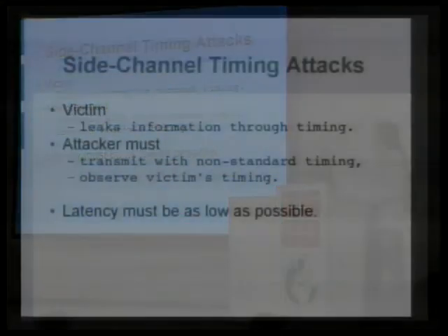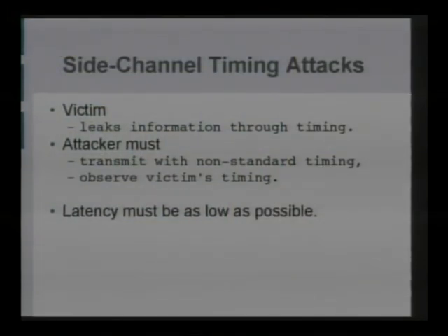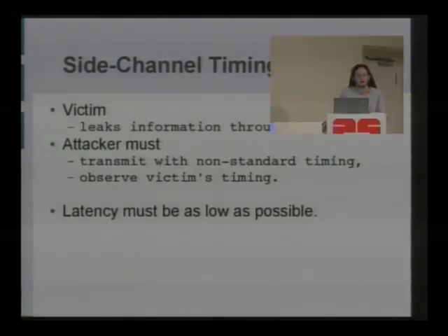In the timing attacks, you send serial traffic with the start bit early, and then you can actually watch how long a password comparison takes within a victim chip. So for about half of the MSP430s, by doing this, you can figure out how correct a password guess is, in like how many bytes out of your guess are correct. But to do this, you need absolutely low latency.